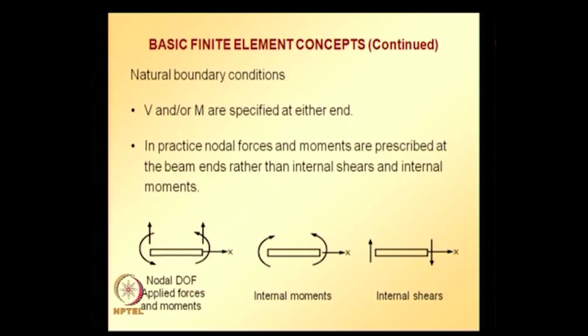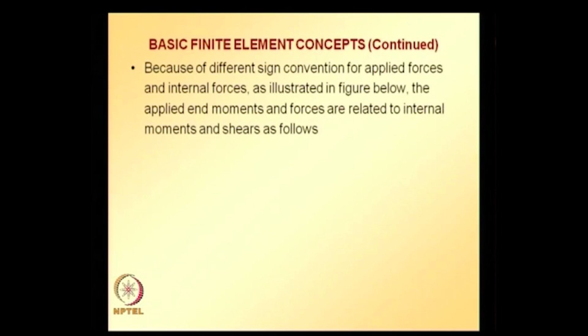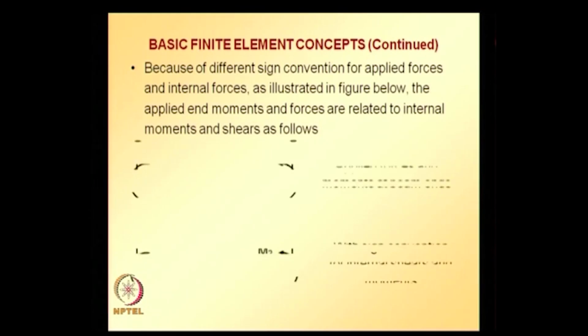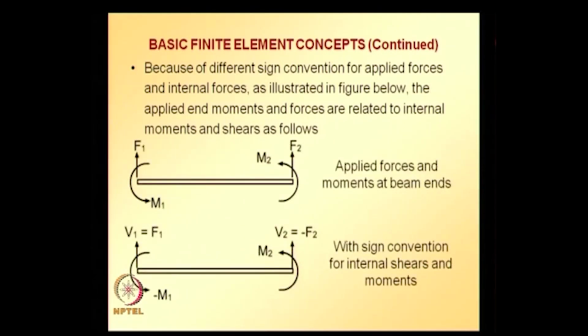Similarly, at the right hand end the applied force is in the opposite direction to the internal shear, whereas at the left hand end the internal shear is in the same direction as the applied force. Because of the different sign conventions for applied forces and internal moments, as illustrated in the figure, the applied moments and forces are related to internal moments and shears as follows.